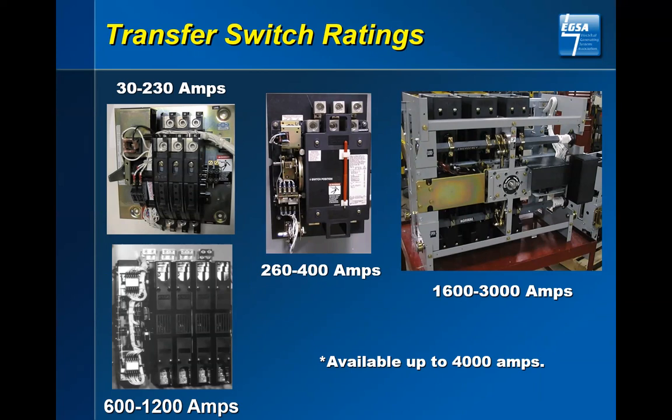So in the upper left-hand corner, this is a little modular. What you see is what you get, WYSIWYG. These are only 30 amp to 230 amp switches. They are a very simple switch, very quickly operated. But when we go back to look at the withstand and close on rating, even at 230 amps, I may be limited to 10,000 amps of fault current. If you're exceeding that amount, you cannot use this product.